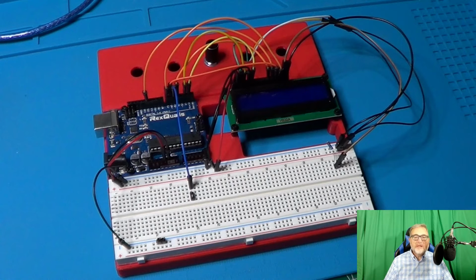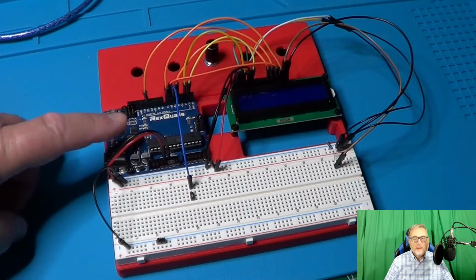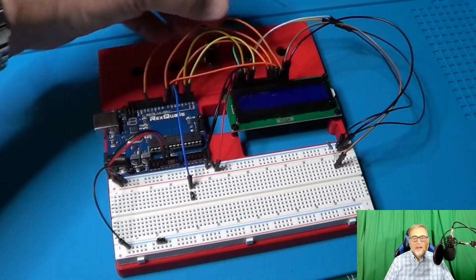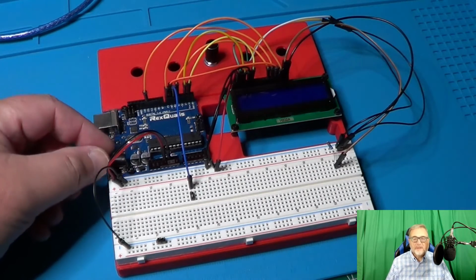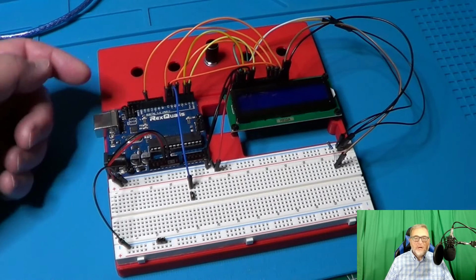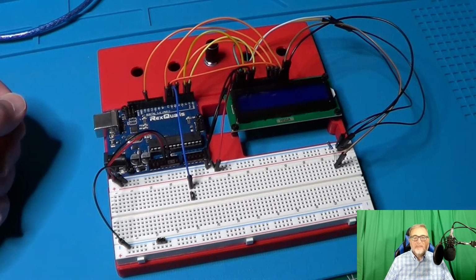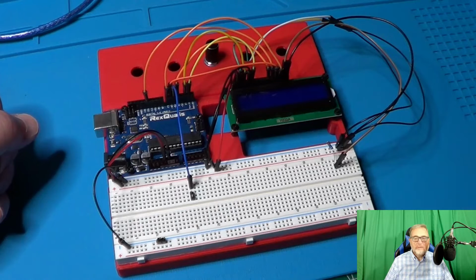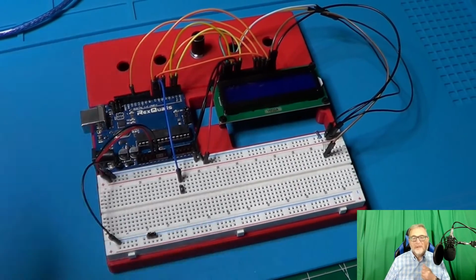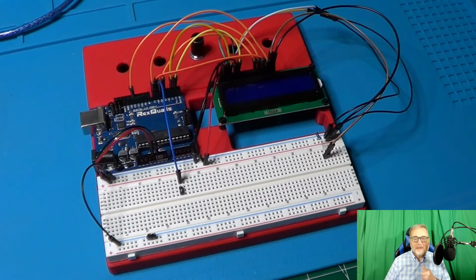Here is our new version of the frequency counter, built around my Arduino prototyping system. Visible here are the Arduino Uno board on the left, a clone actually, the 1602A LCD on the right, and the potentiometer to tune the contrast. I already made all the connections using these jumpers. Such connections are basically the same as in the previous version of the frequency counter, the only changes are on those pins we discussed earlier when we examined the schematic.